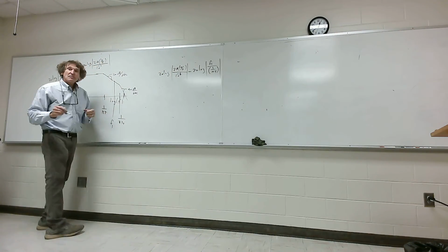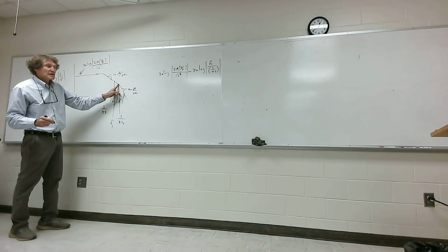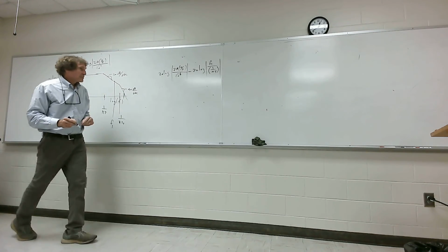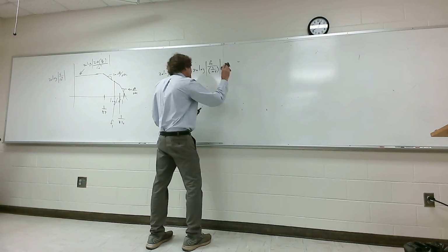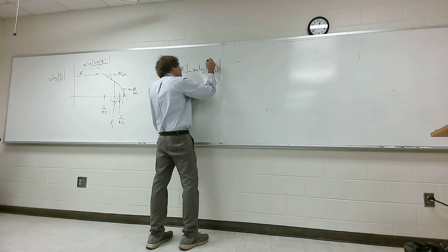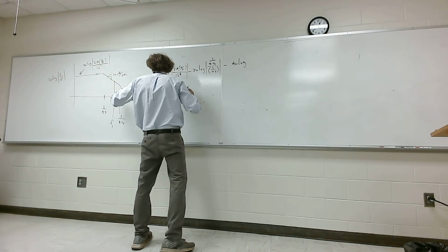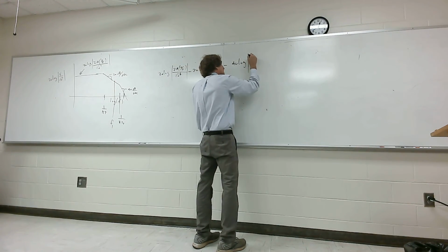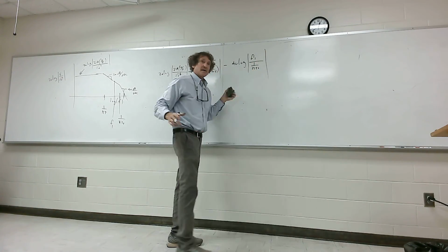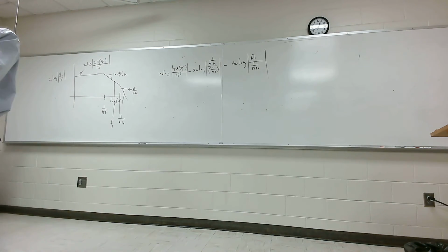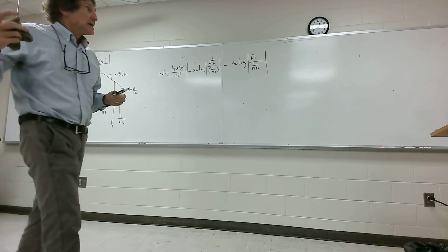Now, if you're beyond that, if you're over here, then what you have to do is first take the full decrease from here to here. So it would be 20 times the log of the second break frequency, which would be 1 over pi tau rise, and then you would have to take minus 40 times the log, because now you're breaking at 40 dB per decade, of whatever frequency you stop at over 1 over pi tau rise. I know I said a lot today, and you can do it. I'm going to give you some problems. I wanted to get this all done, so next time we work a bunch of problems, and you see this worked out.